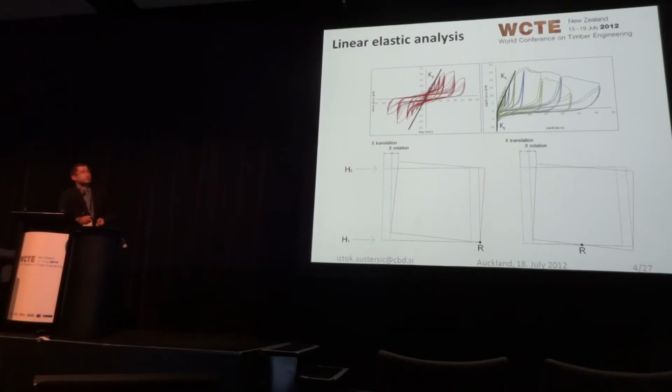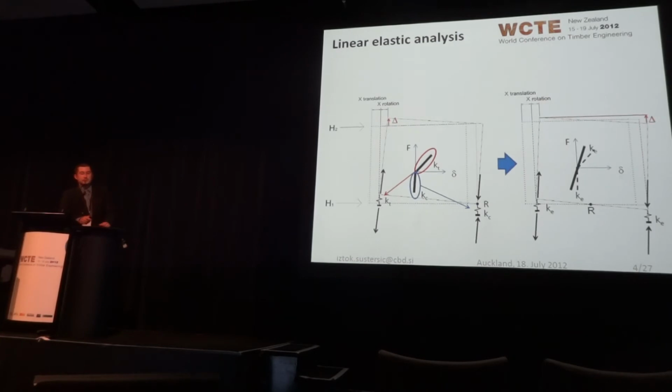So basically you have to translate this wall behavior like shown in this figure. So we move from the tension stiffness of a bracket and the compression stiffness of the wall to an equivalent response of a new calibrated bracket, which responds the same in shear and tension.